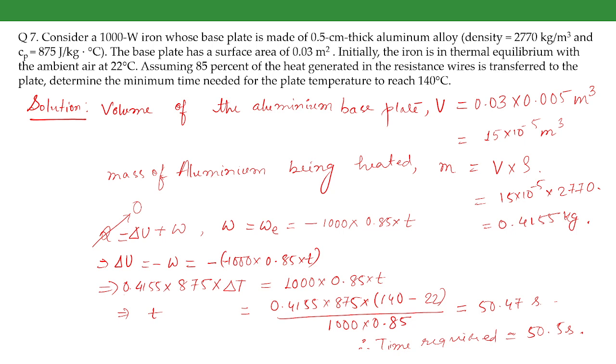what happens is that there is no forced convection, right? How are we neglecting it? Let me tell you. It is in contact with air, right? And air has a very low thermal conductivity. I mean, its capacity to conduct heat is very low. There is no forced convection. You are not turning on a fan while you are heating up an iron, right?